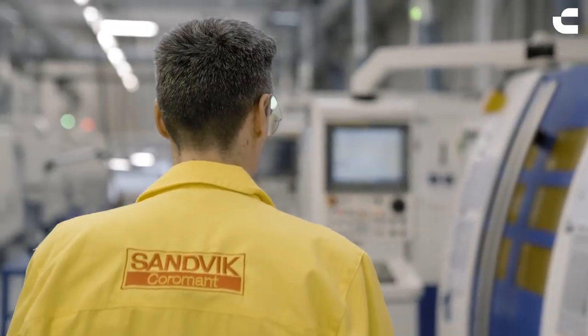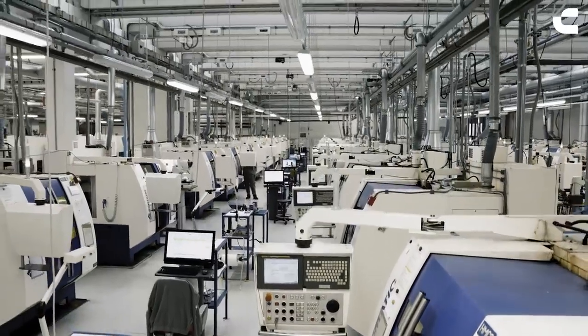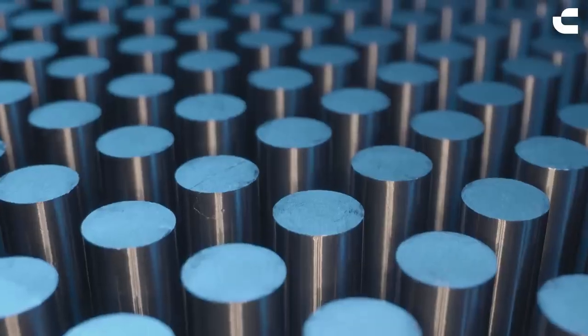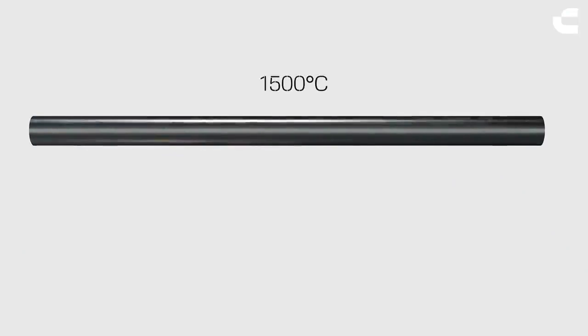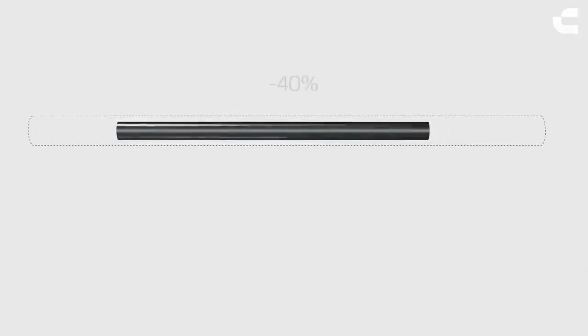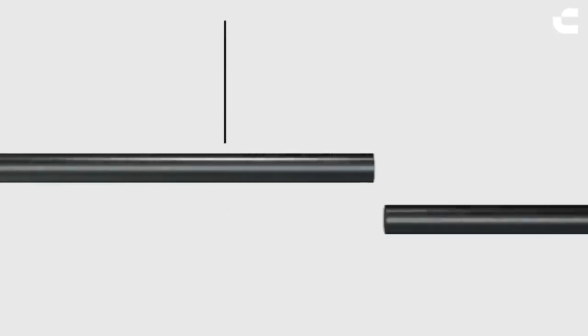Once the technical office is satisfied with the simulation results, the program is ready for large-scale manufacturing. It all starts with the blanks. These are created by mixing metal powder into a dough, which is formed into long rods and sintered in an oven with temperatures up to 1,500 degrees. During this process, they shrink in size by 40%, but still keep their exact shape and form. Quality checks are made, and then they are sliced into blanks.